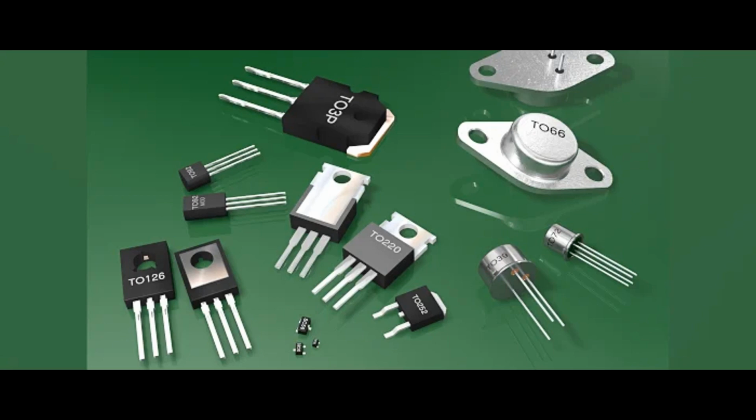Metal oxide semiconductor field effect transistor, MOSFET. MOSFETs are the most widely used type of FET. They consist of a metal gate electrode separated from the semiconductor channel by a thin insulating layer, typically silicon dioxide. MOSFETs are further categorized into 2 types, enhancement mode and depletion mode.